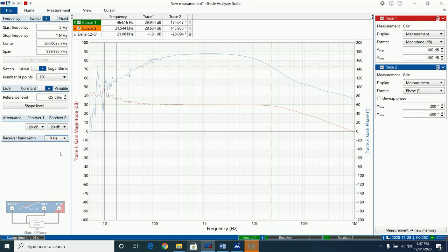Okay, if the bandwidth of the injection transformer was a little bit lower, I am confident that I could get a little bit better fidelity down here. But you can tell that the zero happens around 20 to 30 hertz, and then the pole happens at about 20 to 30 kilohertz. So that's pretty much in agreement with the model as well.